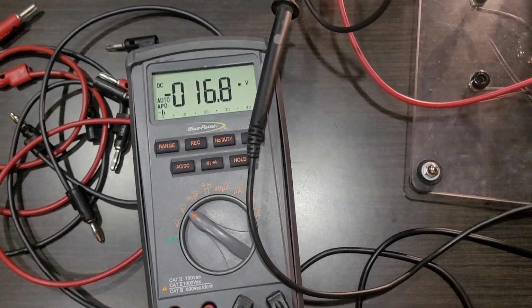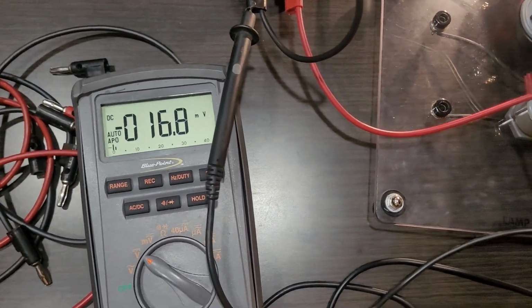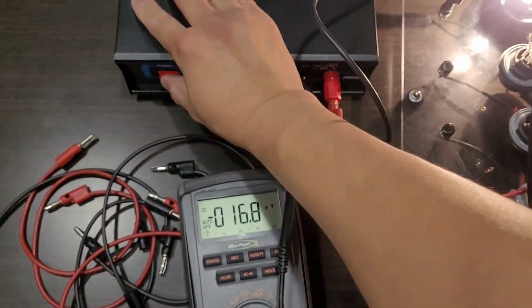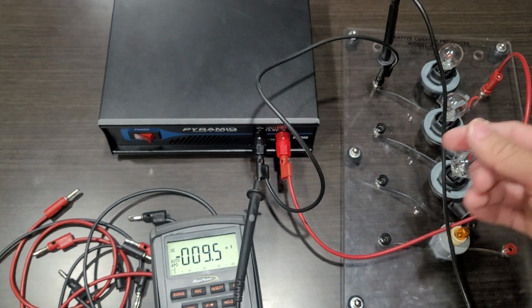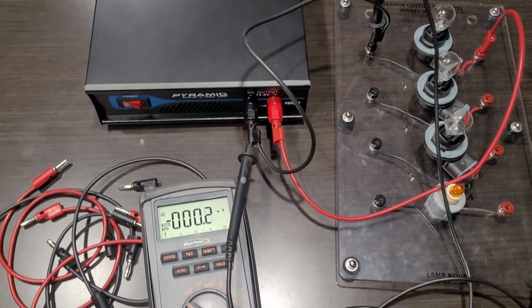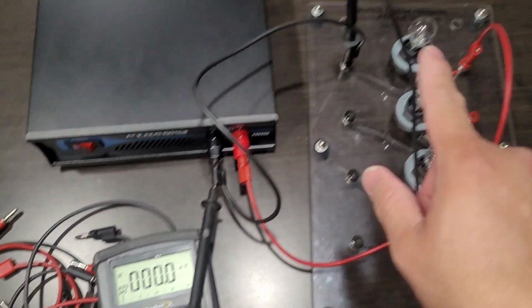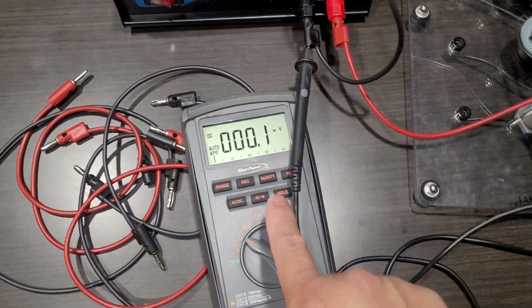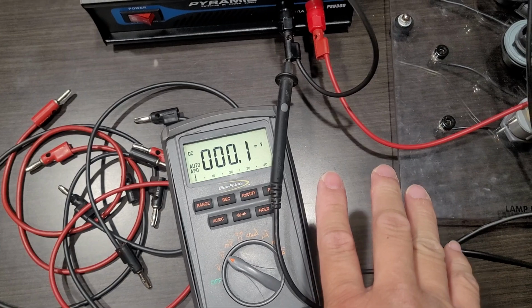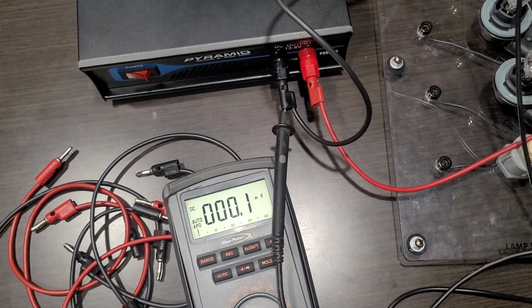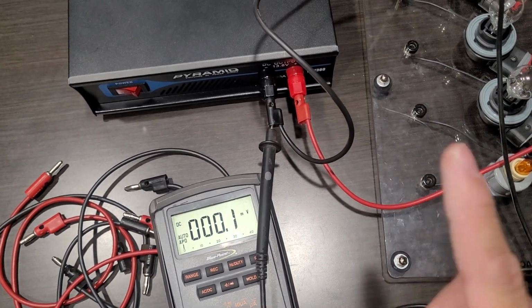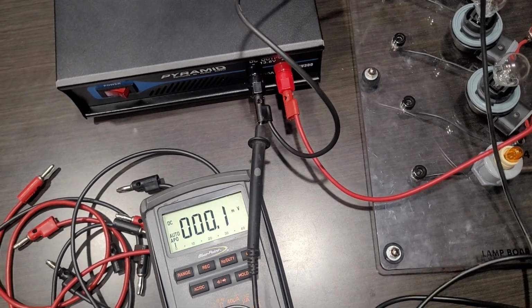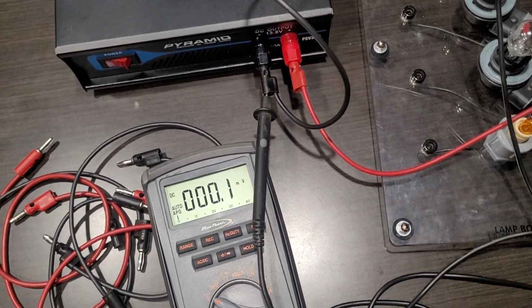Okay. Now, let's go back. I'm going to turn the power off here for a moment because there's a lot of glare here. And you'll notice that when I turn that off, the voltage drop of the wire, again, it's still hooked up, went down to almost nothing because right now there's no voltage in the circuit because the power went off, no current is flowing. So it will not read any voltage values at all.